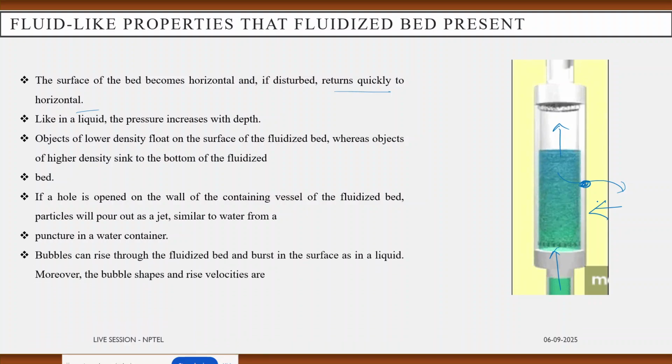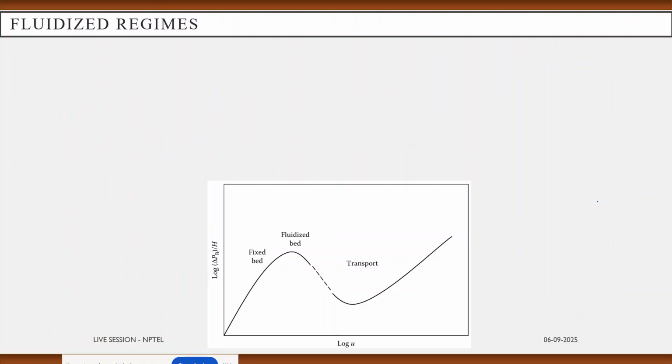The bubbles arising through the fluidized bed will also burst on the surface as in a liquid, and moreover the bubble shapes and rising velocities are similar to those of bubbles in a liquid. So by this we got to know that a fluidized bed also behaves like a fluid. That's why it is named a fluidized bed.